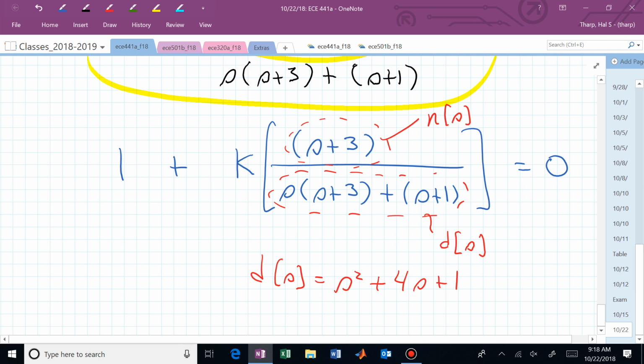Hopefully you say the left half plane, right? Because those two coefficients are present and positive. It's a quadratic. We know immediately if those two coefficients are present and positive, the roots are in the left half plane.